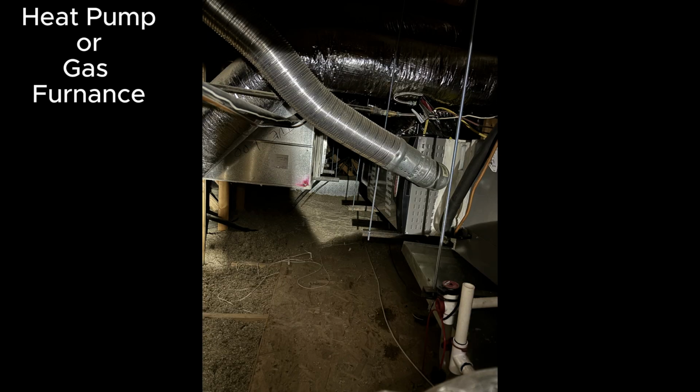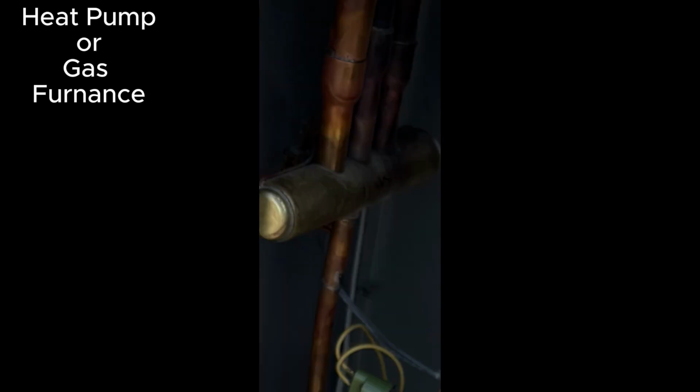Another way you can tell is if you ever were to go into your attic, or if your indoor portion of your AC system is in a closet or somewhere where you can access it or want to access it. You'll see in this picture there's this kind of sheet metal, flexible metal looking thing. That's the flue, and that discharges gas outside of the home, carbon monoxide, dangerous gas. So air handlers will not have that flue. Furnaces will.